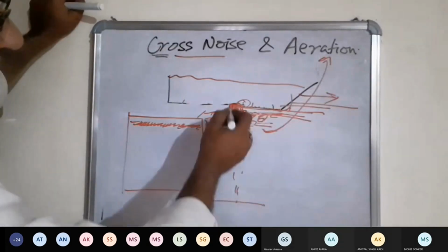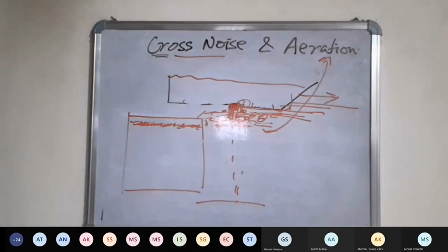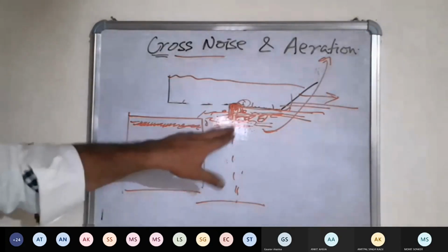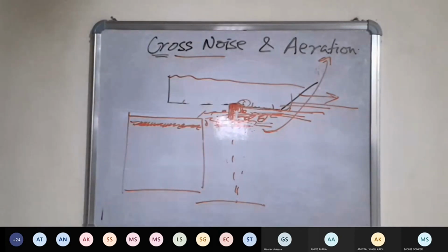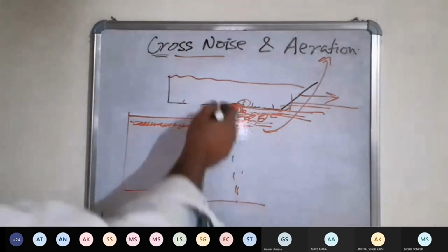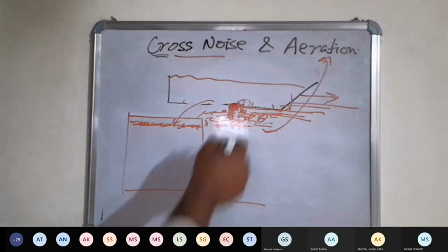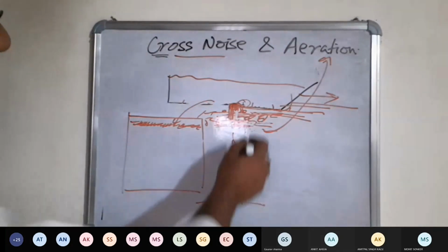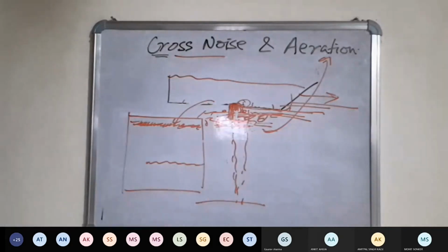Because of air bubbles, the signals are getting obstructed, reflecting the echo from the water layer itself, and so it will result in a dark line near the zero line. Part of the energy will be transmitted and then received, so depth also will be read.